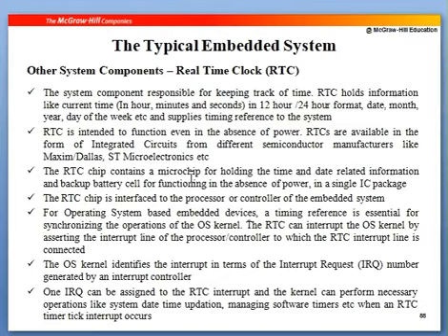All this is due to the unit you call an RTC, a real-time clock unit, which is interfaced to your system. This real-time clock unit requires very low power, and it will run for years without any issues. This RTC also has a battery backup; since it can work with small power, a small battery is provided to it, and it will give you the time, hours, minutes, seconds, even the date, month, year, all that information, if you require it.